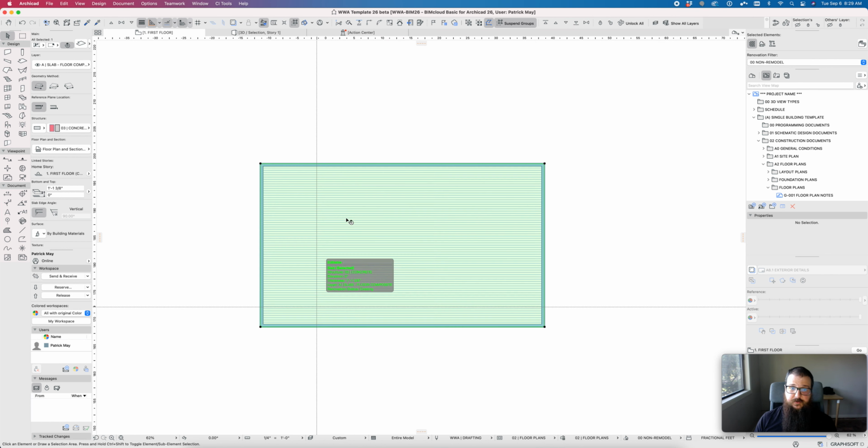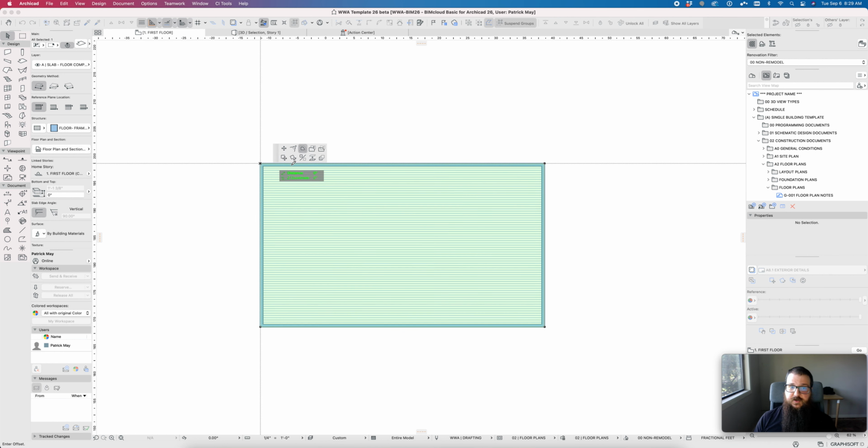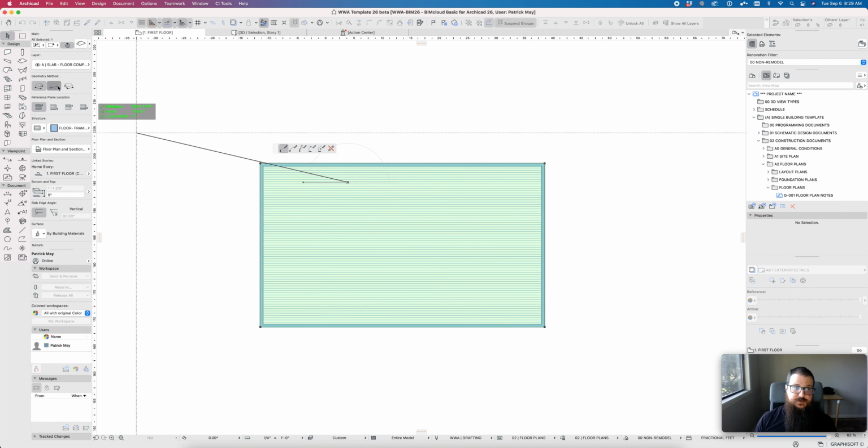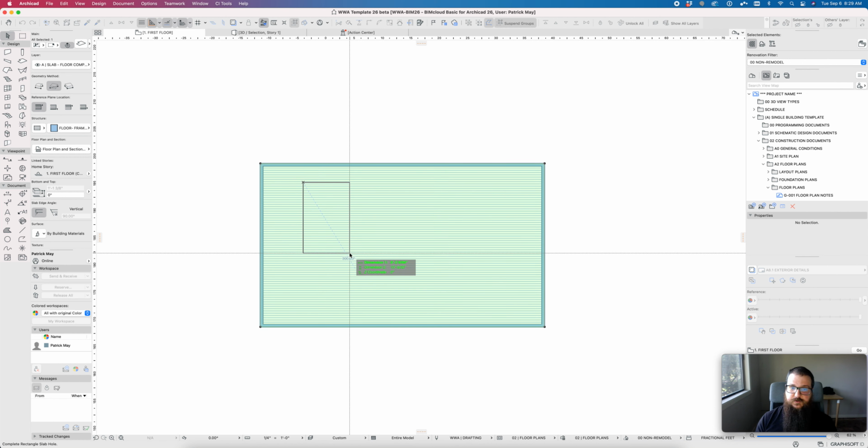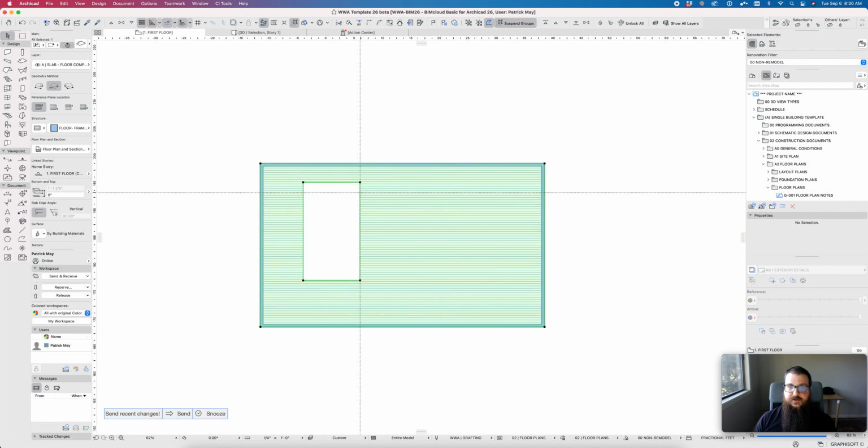It's pretty simple. There are other pet palette options for the slab. Like we looked at before, you can offset edges, you can copy and offset edges, you can subtract out geometries from that slab, and this pulls from the geometry method here. So this works really well for creating stair landings. So we could say we have stair openings within the floor. So we say we have a stair opening of 10 feet in the X direction, Y negative maybe 18 feet or something, and then we get our stair opening.